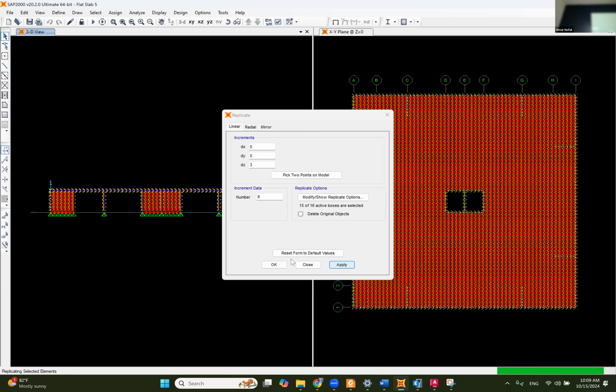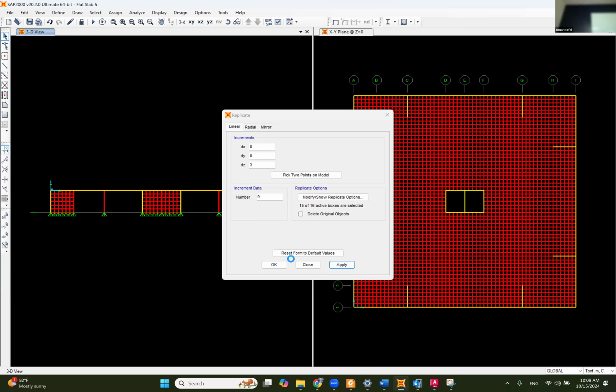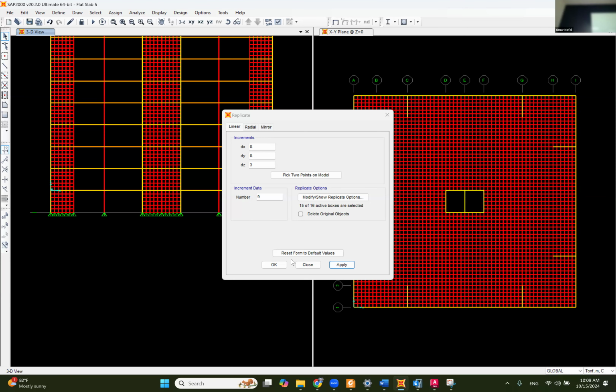Well, the thing is the final design of the column. We get the preliminary dimension based on the 2D model, based on the vertical reaction. Let's say that you get a column, for example, 50 by 50 centimeter. Once you have this column, we put the column with the exact dimension because this is the stiffness that is going to absorb lateral moment. So we put them in the 3D model and then hit with seismic and wind and put all the load combinations that we have.